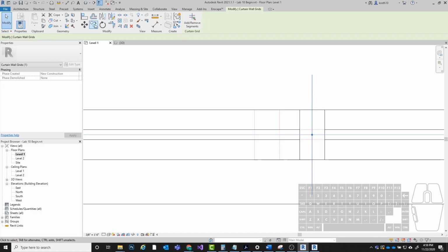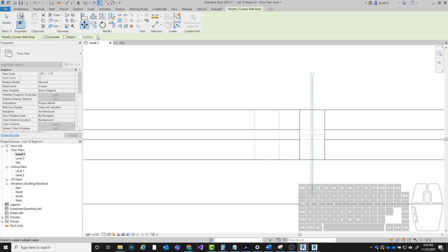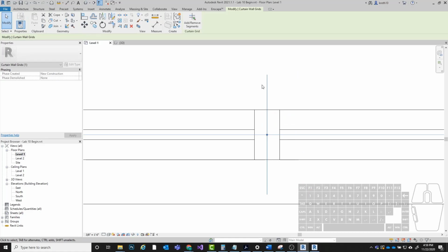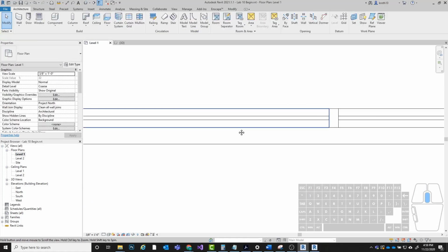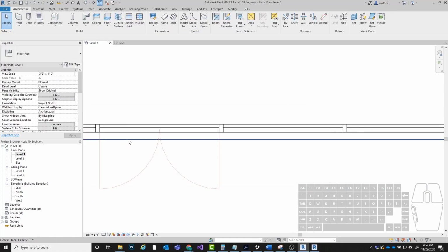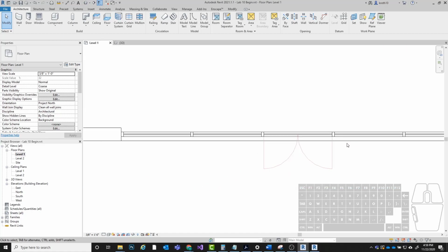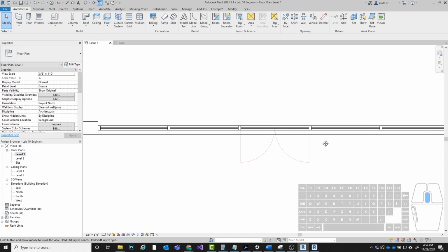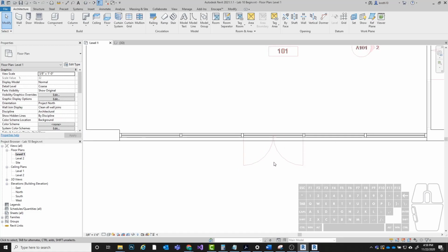tied to it, and then we have to move it, so use my move tool, and then we can click on the edge of the mullion, okay? And then we can move it back to the left until it's aligned, all right? So if yours is messed up and yours aren't in the right spot, that's how you can go about fixing this, okay? All right, so mine looks pretty good. The next step is going to be adding in this door right here.